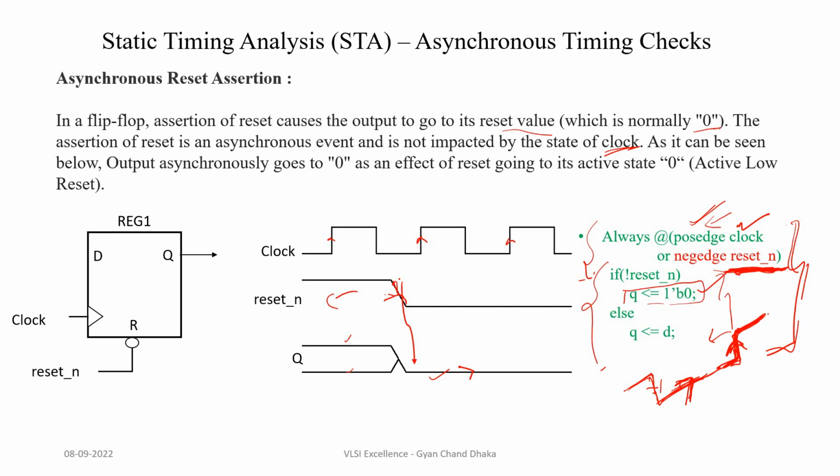Even if the reset assertion happens near the active edge of the clock, then also for some time the flip-flop might go into metastable, but usually the reset signals are expected to be applied for quite a long time, and in that case, finally our flip-flop will settle to the reset value, and there won't be any issues in the design because of this small metastability caused when reset assertion happened, because finally the flip-flop will be in the reset state.